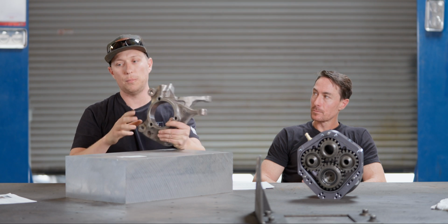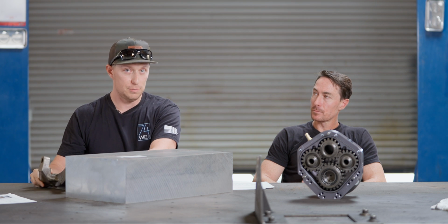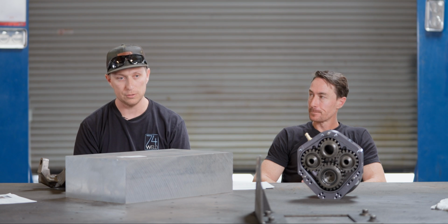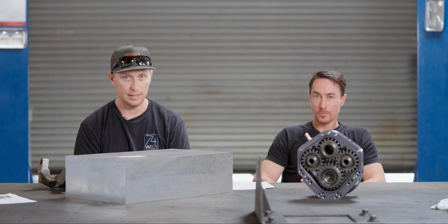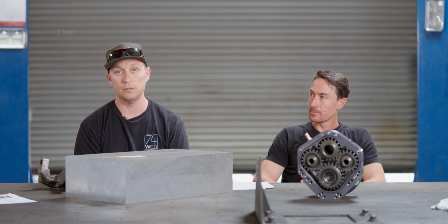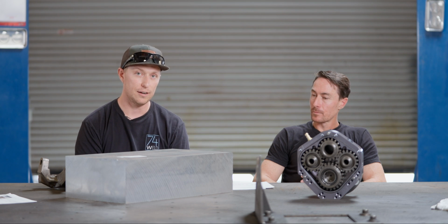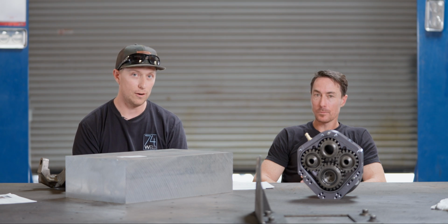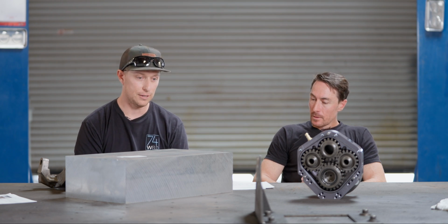In the case of an upright, it's actually part of your suspension. It's suspending the vehicle. So now you're adding leverage to things, and the forces you're going to see on the material are much higher. You're asking it to do a lot more. Yeah, so that's a big reason.